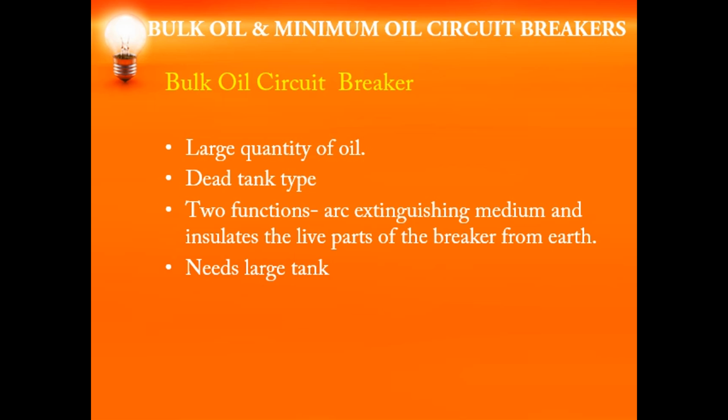When you have a large quantity of oil, whenever the arc is quenched, carbon particles are generated. What will happen if a large amount of carbon particles are generated due to heating of the oil? The insulating property of the oil will get reduced. So you need regular maintenance, and since a large quantity of oil is required, replacing it again and again is a huge cost, and maintenance is more. That is why, instead of going for a bulk oil circuit breaker,